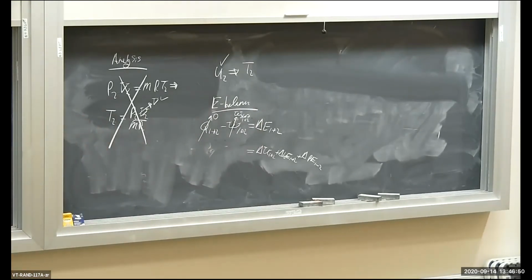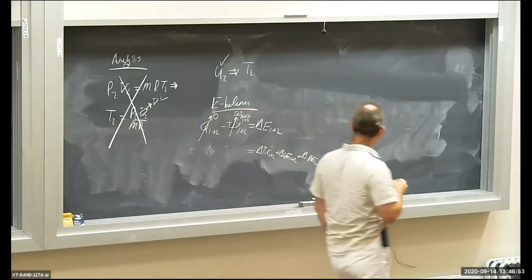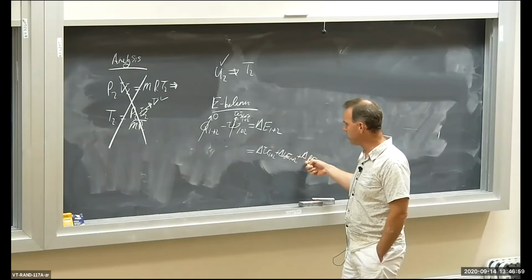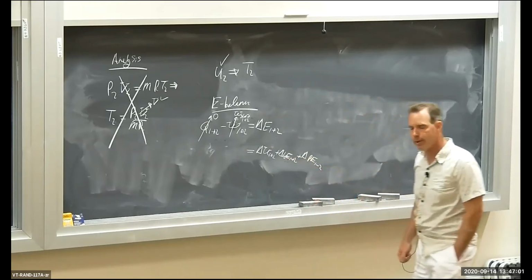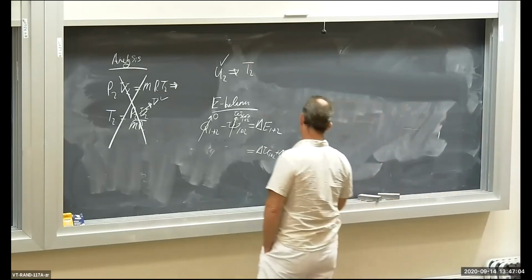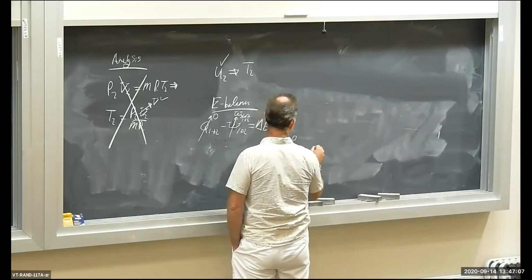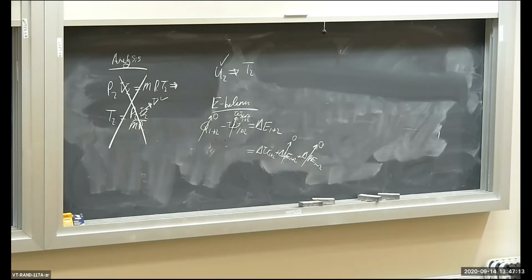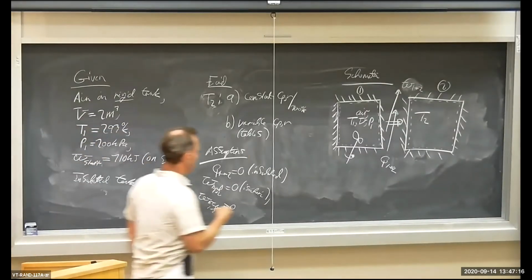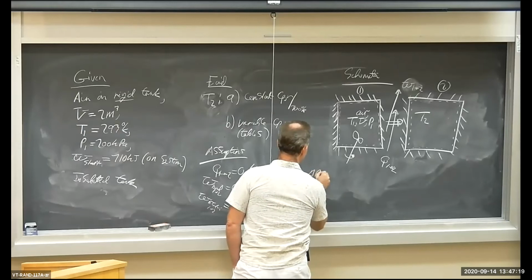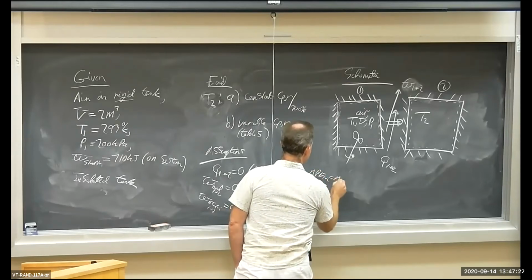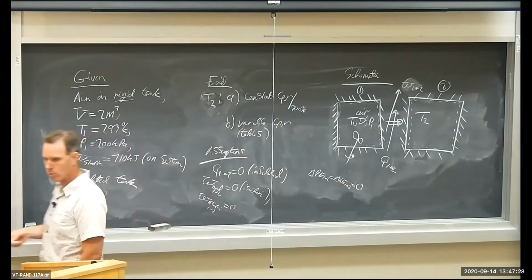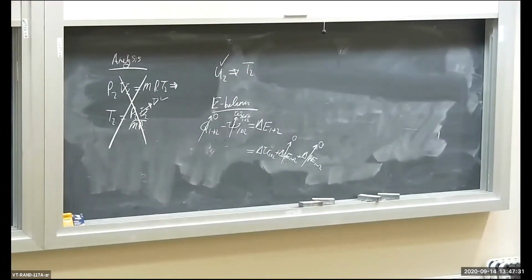Now let's tackle the right-hand side, the change in energy. We don't know anything about the container in terms of its position or its velocity. There's nothing in the problem statement about it moving or accelerating. So I'm going to write it down in the assumptions: I'm going to neglect changes in kinetic and potential energy. Delta PE equals delta KE, and they're both equal to 0.